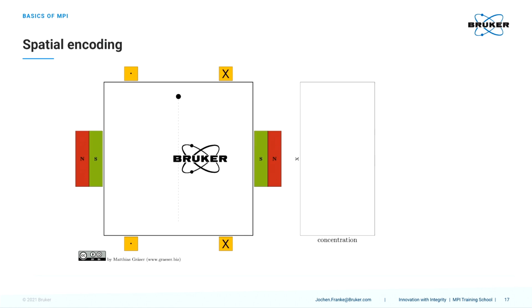So now consider we have a phantom and we do this line scanning as just described. We go through with the field-free point, acquire the data, make the corrections, and plot in grayscale, step by step in line scanning mode. So you can see that we can reconstruct at the end a phantom or the image which we have placed in our magnetic particle imaging system.